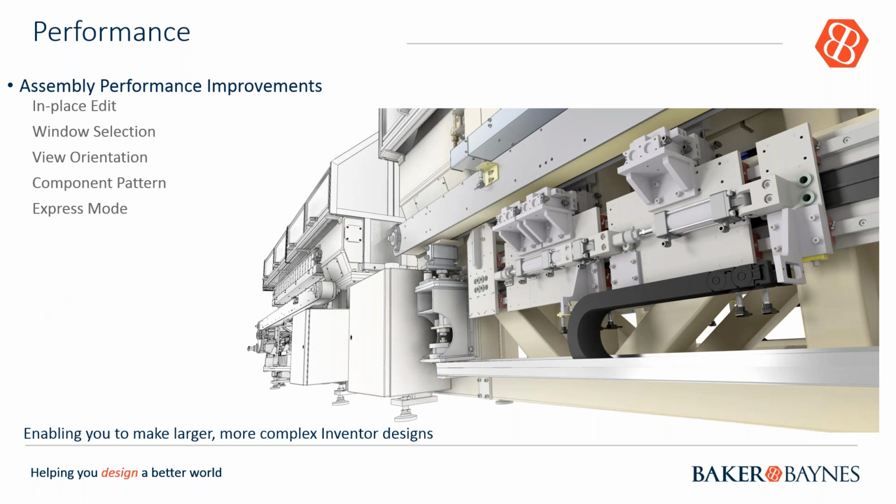Also, patterns now use the active view representation, not the master view representation. Pattern compute performance is improved, so when you're using the pattern command, the computing performance has been significantly upgraded. Also, using the visibility toggle in the marking menu and the context menu is faster for deep-level components in large assemblies.